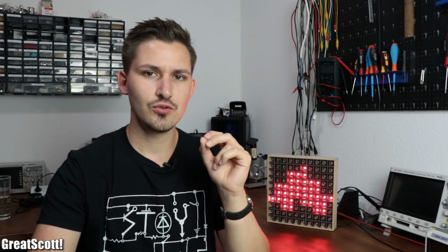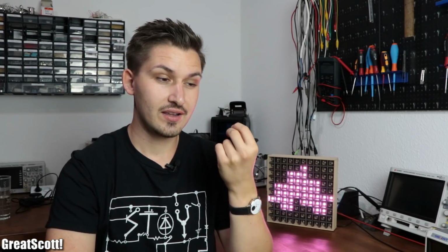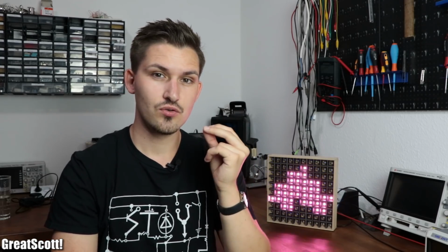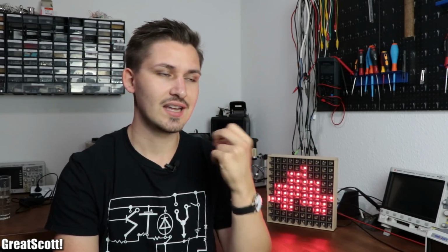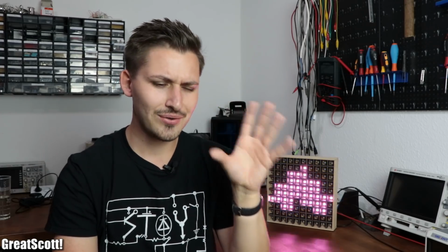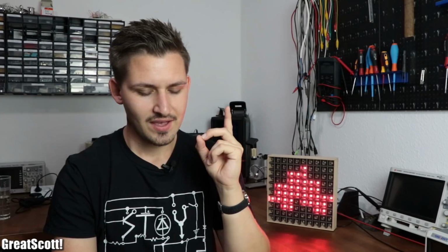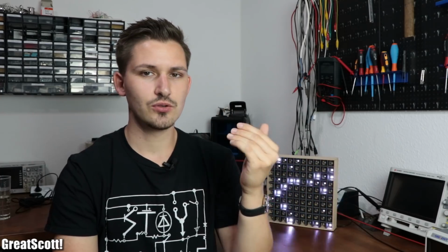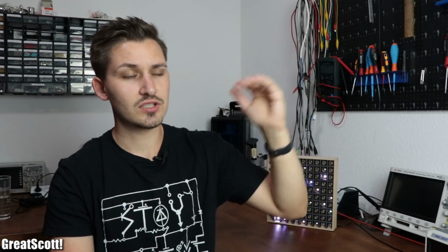It is recommended to use a PWM with a high resolution. So the Arduino has 8 bits, like 255 steps, but it would be great if you had like 10 bits, 1023 steps, sorry, or 12 bits, 4095 steps, I think. With those, the way to go is you have 1 PWM channel for each color, and then you just go through the lines.